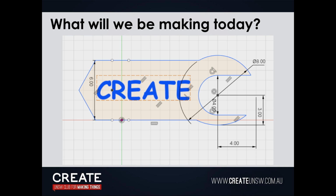You can drag that down. Fusion's pretty good about snapping things. So that's snapped to it. Hit OK. Now we'll just draw another arc here, just to finish the handle off. We'll do a center point arc.